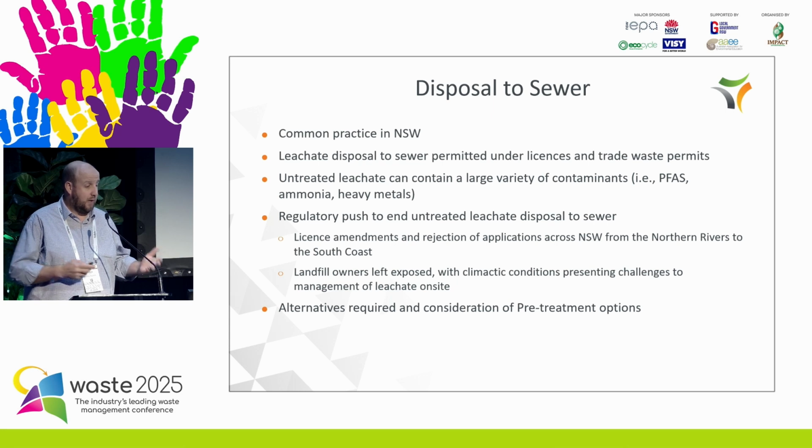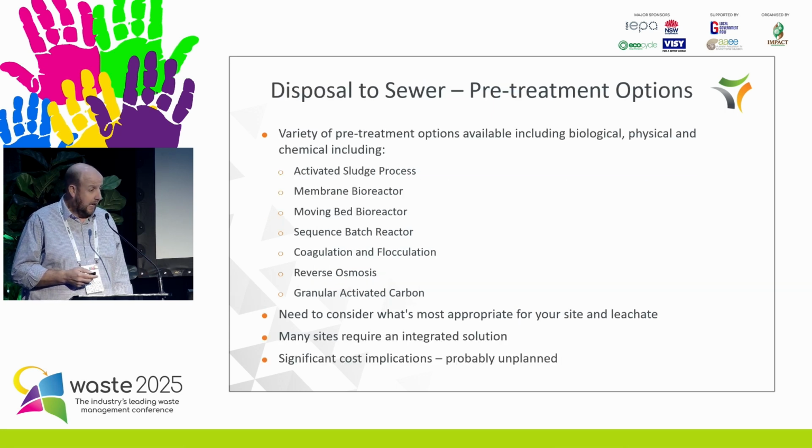Obviously, if we are going to sewer or a wastewater treatment plant, the push is towards pre-treatment. I've been talking to many people here at the conference about pre-treatment options, and there are plenty of people who have far more experience and knowledge of those than I do, but there is a range of them that you can use. Realistically, it depends on your site location, your concentrations, what's in your leachate, even the volume you have, and also what you're trying to do with it. So there's a variety of options, which I've listed up there: biological, physical, or even chemical treatment.